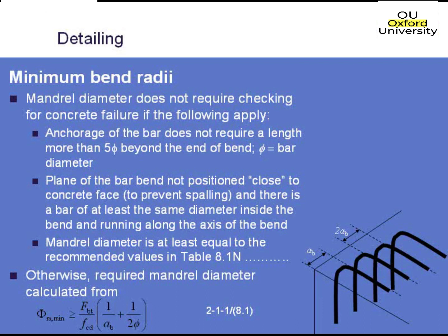If you look at the Eurocodes, the compressive strength that you're allowed to use cannot exceed C55/67 concrete. If you do exceed that, you'll have to reduce the value for that equation.